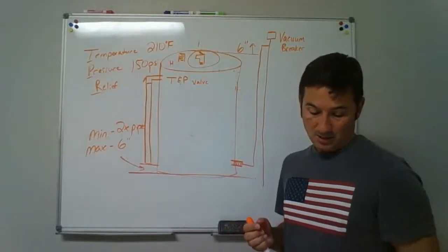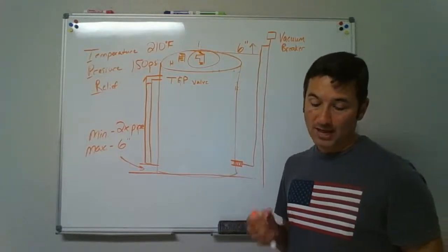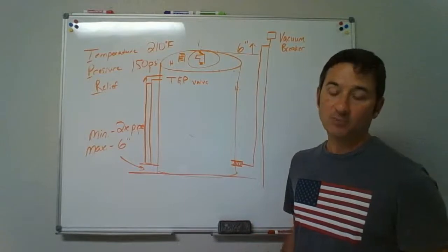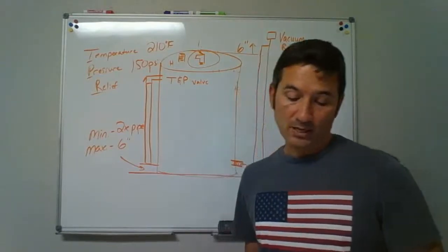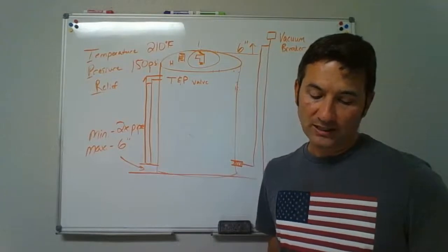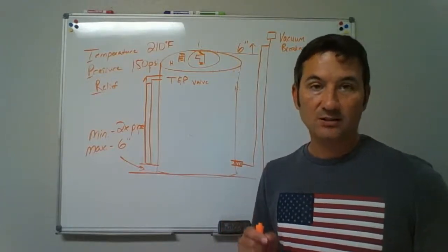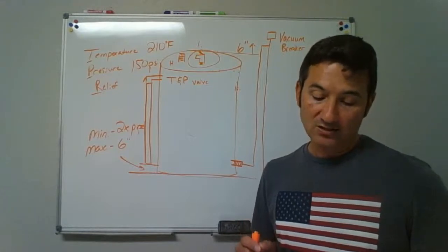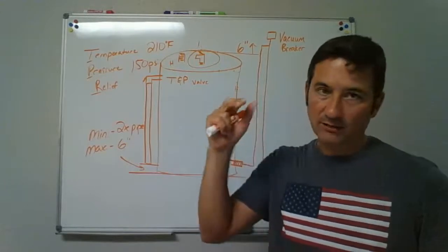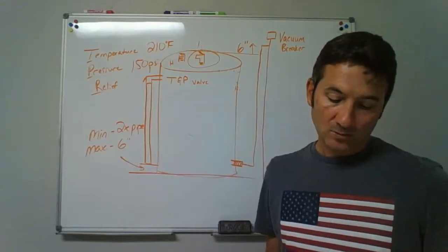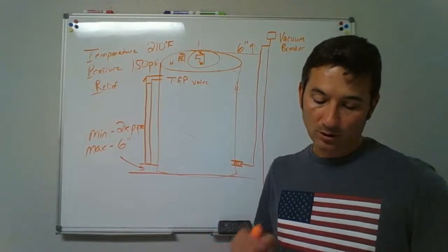Okay. And then it talks about 504.7, a required pan. When do you have to put a pan on these things? Where a storage tank type water heater or a hot water storage tank is installed in remote locations, such as a suspended ceiling, attics, you've got to put a pan. Above occupied spaces, a second floor level up, you've got to put a pan under it. You don't want that thing to leak and then do damage down to the ceiling and floor below.